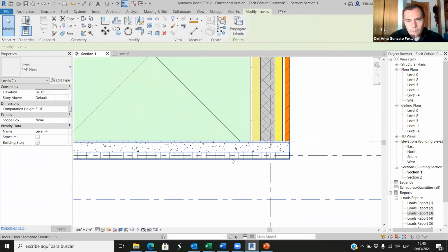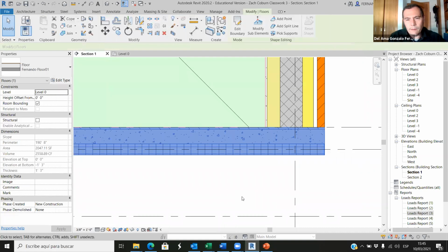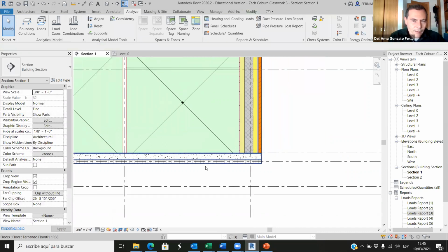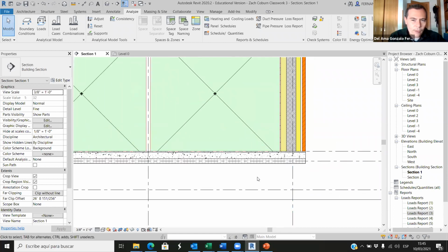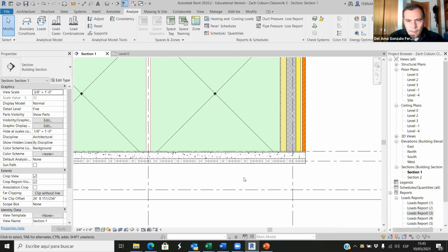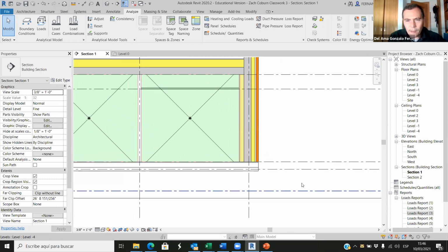So this is the floor. We have the flooring, then the slab, and finally the thermal insulation material. And here we will have either soil or aggregates. That will be soil, okay, because this rigid insulation is resting on the soil. We don't have a crawl space. That's the other option that I want to explore, but not now. So today we imagine that this is soil.